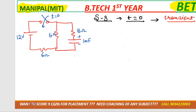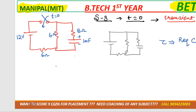Now tell me, at t equal to 0, is the switch closed or open? Closed. Let's redraw the diagram. It is closed. Resistor as it is, resistor as it is, resistor as it is, and capacitor as it is. Correct? Now what we need to calculate over this is tau. The tau formula is R equivalent multiplied by C.